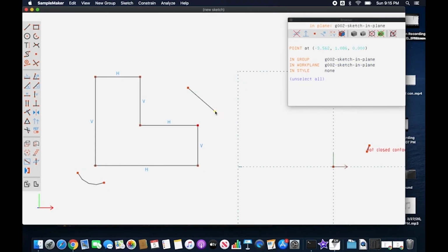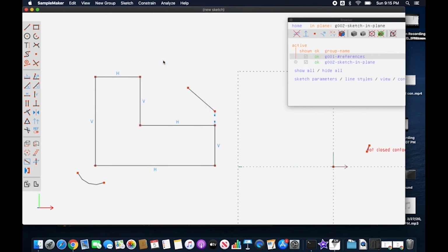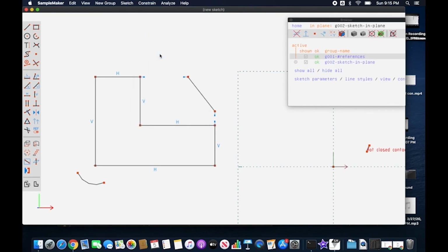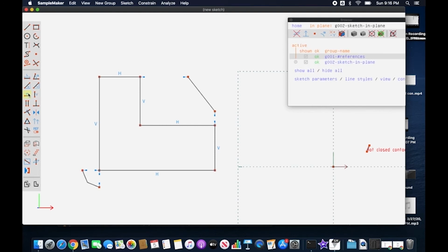In this section, I'm going to do some vertical projections, and you'll notice when I come in and do them, which is going to be Shift V, it matters where I click first. So I'll click here first, and then I'll click to this point, and then when I do my vertical projection, you'll notice that it went up to that point. If I pick that spot first, then this one, and do a vertical projection, it'll project to there. If I do here, I'm going to swap back to a horizontal. So I picked that point first, and it moved it up to that spot.